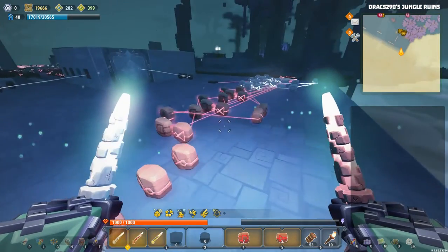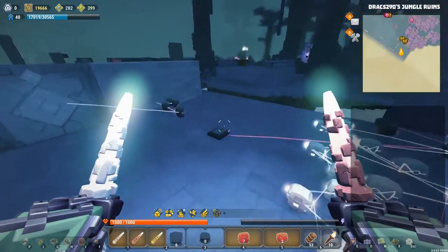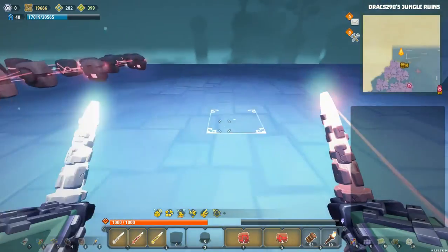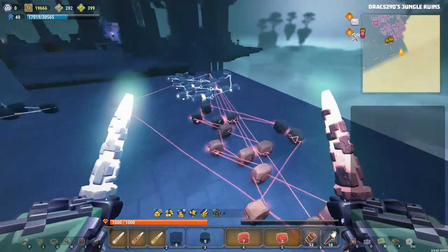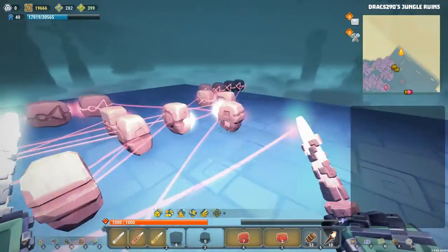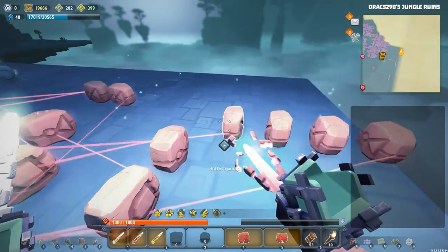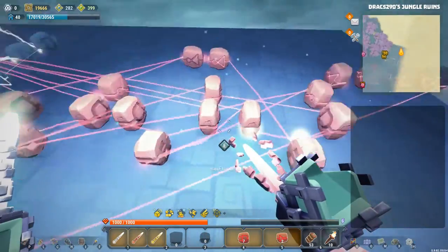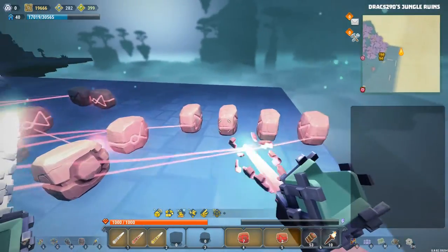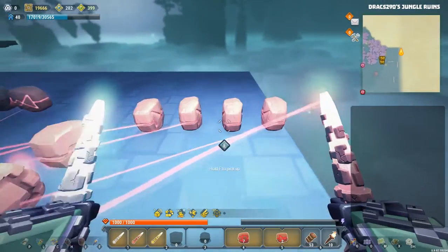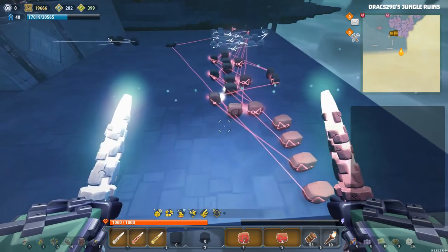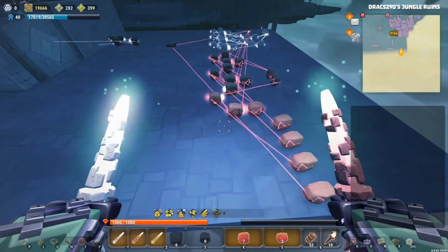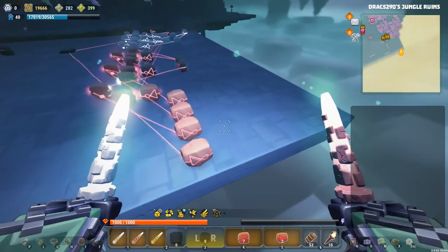So what we're going to do is we're going to hook all of those up right now. We're going to take from the input and run that down into our furthest NOT gate all the way down here. Then we're going to run each of these latches in the red down into their corresponding NOT gate in this series. So here we go, NOT gate, and NOT gate. Now at this point the circuit is getting a little bit complicated, but basically you just need to do this slowly and in order, and everything should turn out okay.